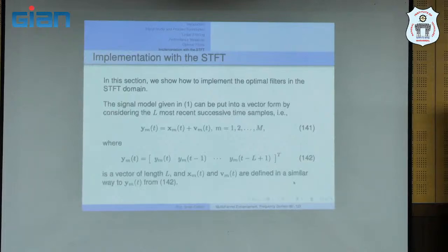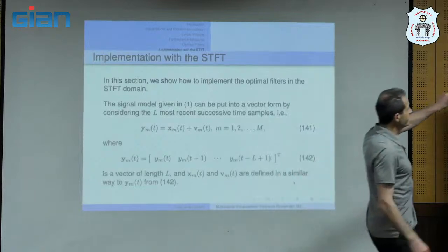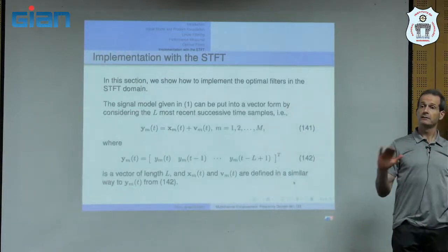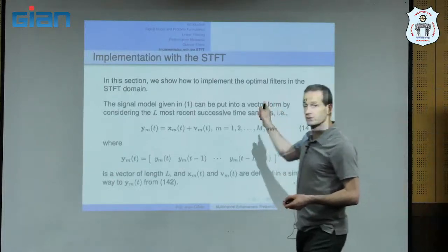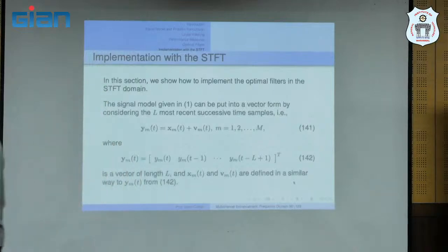So we talked about implementation in the STFT domain for single channel. We also have implementation in the STFT domain for multi-channel. How do we do that? We take the short-time Fourier transform of the signals for each sensor, and then we work on each frequency bin separately. All the filters that we saw before, we just use them in the STFT domain. So it's very similar to what we did with single channel, when we do it with multi-channel.